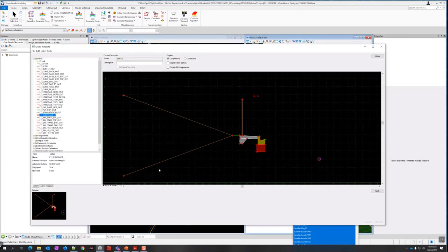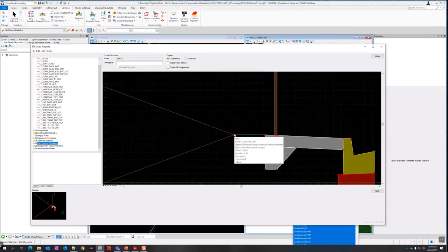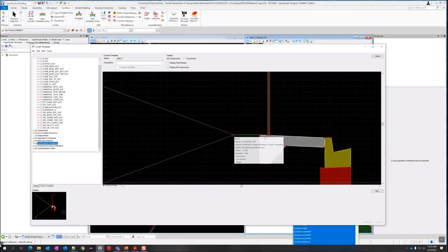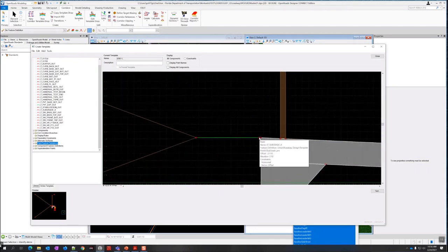So this part, the cut and fill, these aren't subgrade, but you're going to need them as well. So just make sure that there's nothing vertical there either. That's the same thing. You're going to have an issue with the proposed surface. So as long as this line here, only need it for subgrade. So this one has a subgrade feature definition.